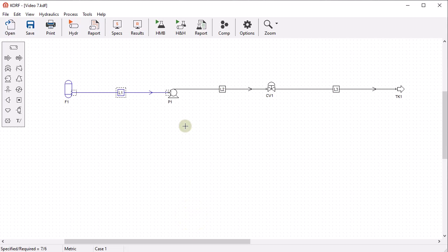accounts for the decrease in pressure due to the increase in velocity at a vessel or tank entrance to a pipe. Thus, the user typically never has to add an exit loss of K = 1 to the fittings of any pipe. Only the frictional loss of typically K = 0.5 from a vessel or tank.